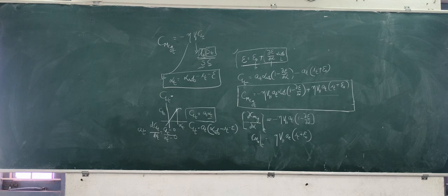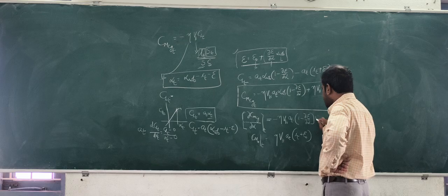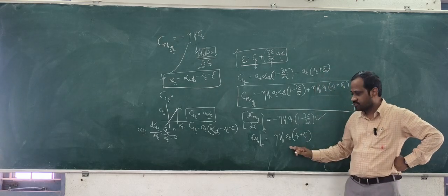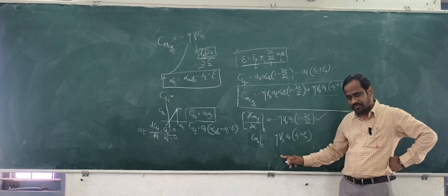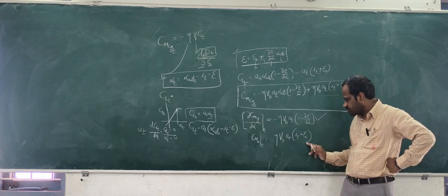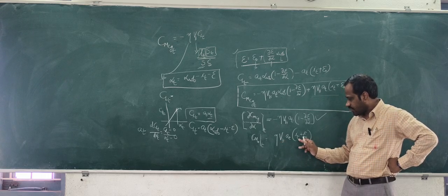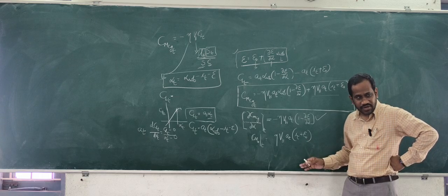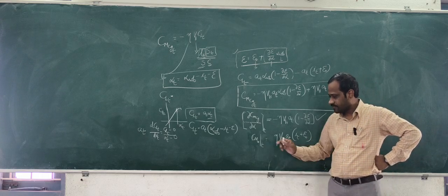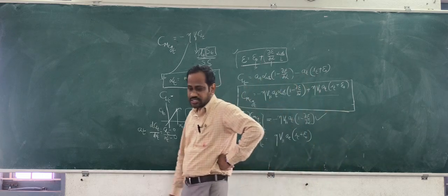It creates a restoring pitching moment to the aircraft. The disturbing pitching moment is opposite to this. Okay. CM naught should be positive. Whether really positive, looking at the parameters. This is positive. VH is positive. Slope is positive. Difference should be IT plus epsilon naught. Is positive or negative? So CM naught is positive.